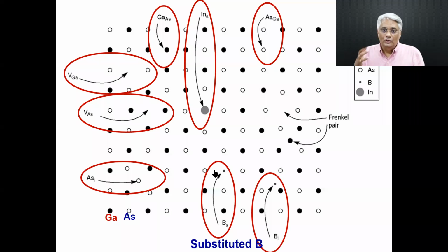Okay. So this is also called impurity doping, because these are basically impurities. When I'm bringing in indium into pure gallium arsenide, what am I doing? I'm replacing, you see, the gallium side with indium, right? So I'm creating a little bit of impurity in the lattice. To what extent indium can replace gallium, whether it is 3 atom percent or 7 or just 1, that is called the solid solubility. So thermodynamics determines that.